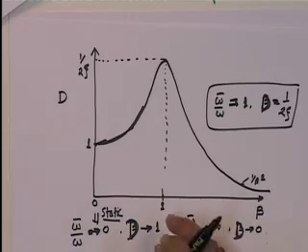What does that mean? Well, all it means is that if you have a static load, there is no dynamic amplification. Well, it is a tautology, right. The more important thing is when the excitation frequency is exceedingly high relative to the natural frequency. Remember that. You see, this is all relative, omega bar upon omega.